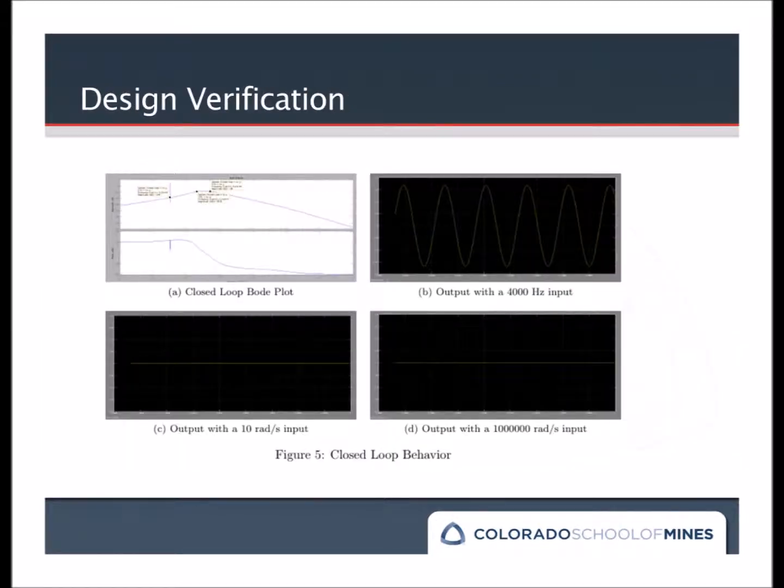In order to verify our bandpass filter rejects and accepts the correct range of frequencies, we ran a variety of sinusoidal waves through the loop. At an input of 4,000 Hz, which is within the frequencies that should be passed, a signal is obtained. At frequencies both below and above our range, no signal is obtained, as shown in the other graphs. In this case, no signal.